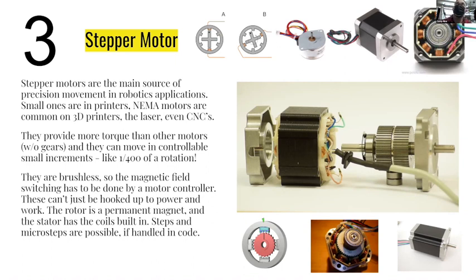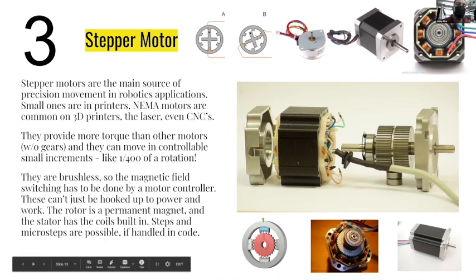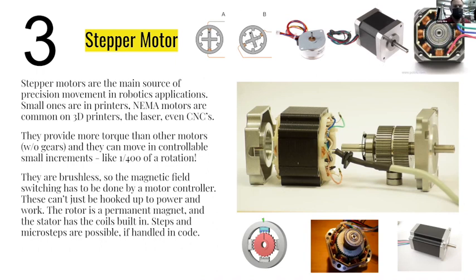They come in lots of different sizes. There's these little ones. Any inkjet printer you've ever used had stepper motors inside to designate all the motion that the inkjet head needs to do. But then these are NEMA 17 motors, or NEMA motors. They have that square profile. NEMA is like a screw hole dimension so that you know exactly how to mount them. I think it's 17 millimeters across diagonally for a NEMA 17 motor, which is the standard size for most 3D printers.